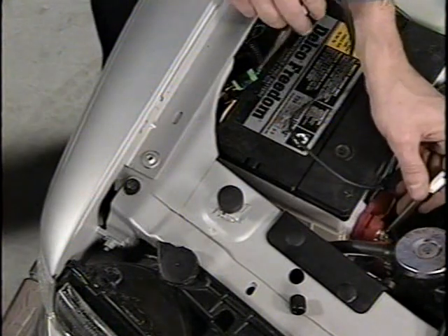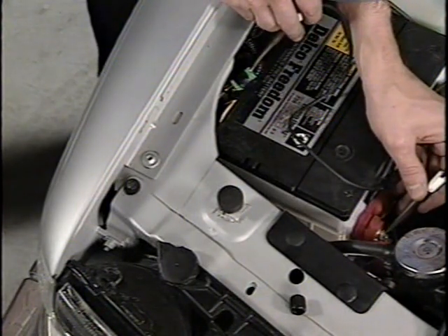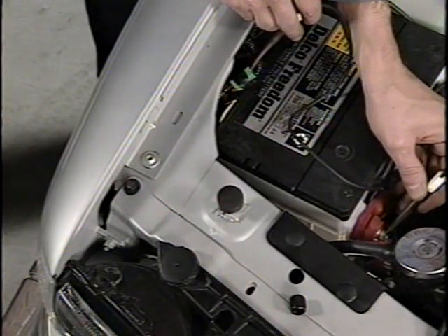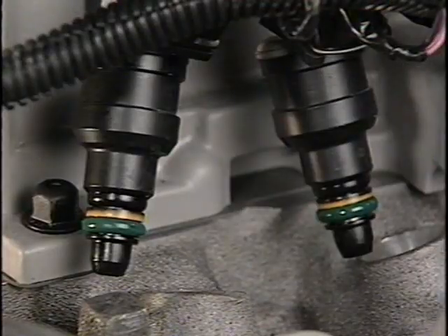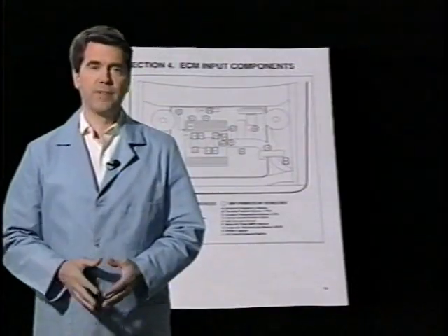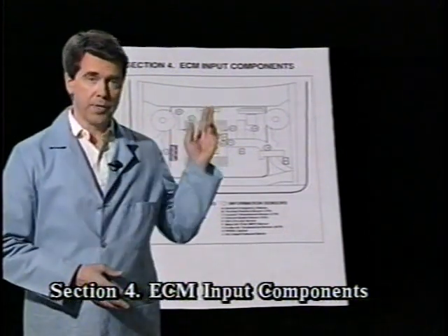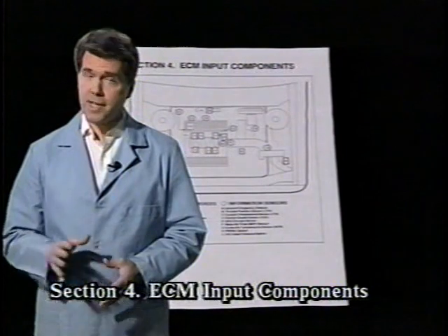Then, with a jumper lead installed to the fuel pump test connector, check for drops of fuel building up at each injector tip. You should clean or replace any injector that leaks more than one drop of fuel in 1 minute. The fourth section of the reference manual explains ECM-PCM input components, more commonly known as sensors.